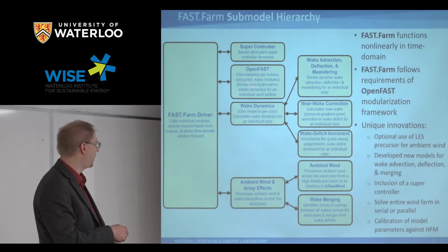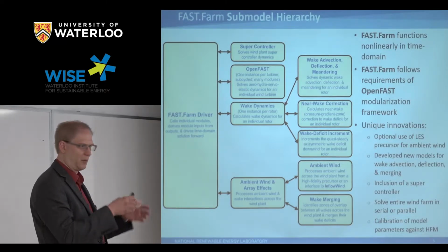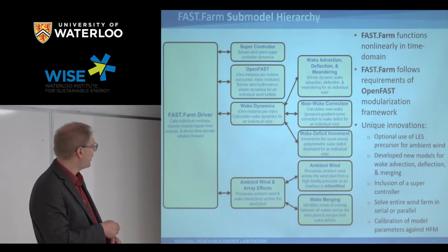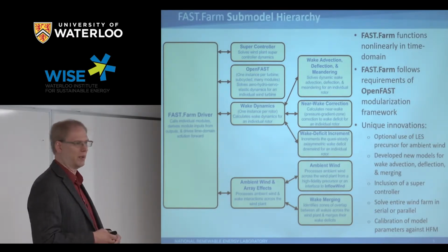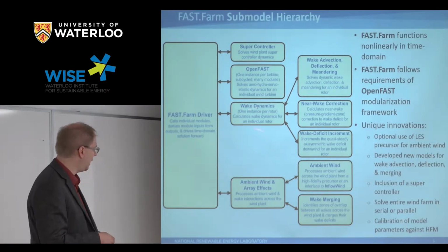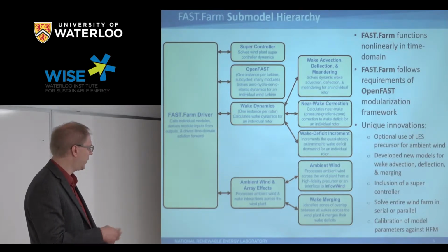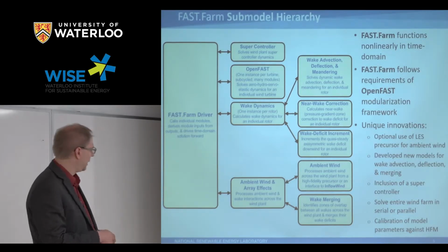And so you say, how many turbines do you want in the wind farm? 10, 20, 100. You dynamically allocate that and make a turbine model for each turbine you're interested in. We also have a block that's the supercontroller, which is the wind farm level controller, so it communicates on a time-step basis with what the individual turbine controllers are doing. And then, of course, the new physics in the model is, first of all, we have a wake dynamics engine that's really trying to predict what happens behind one specific rotor in the farm. And we'll talk a bit more about that.